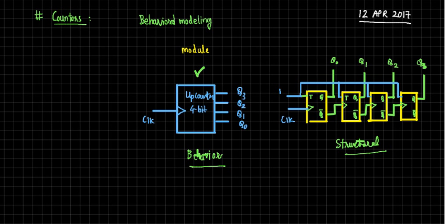Okay, from the left, clock, yes. So clock is applied here first, so this is getting toggled more frequently. The bit which toggles more frequently is the LSB, isn't it? See, if these are the bits 0001, 1011, which column is toggling fast? This one, right? It is 00, then it becomes 11. It is 0101, fast toggling. So that's why it's the LSB.